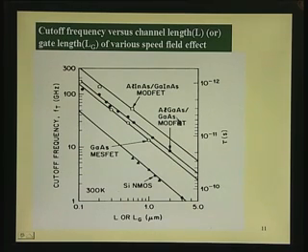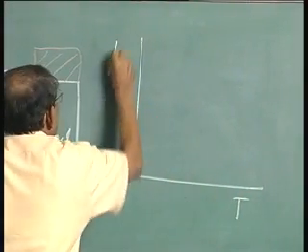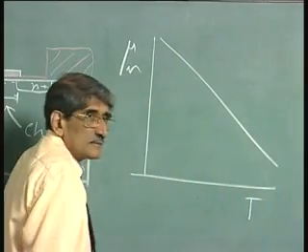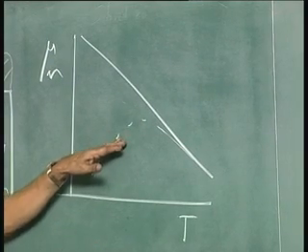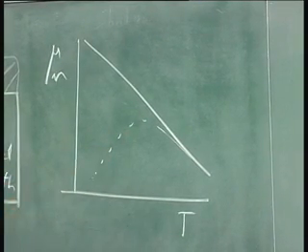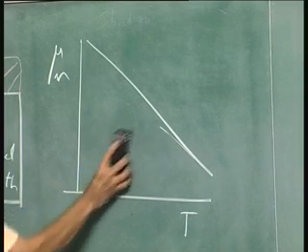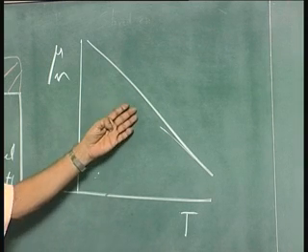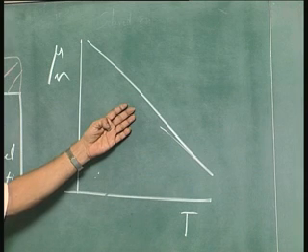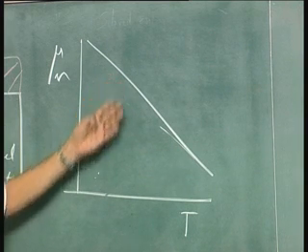Okay. And here if you go to lower temperatures, you can get this curve up even further, because if you remember, we plotted the temperature versus mobility like that, and you had this curve here. I am removing that. That is the lattice scattering mobility. By separating the donor from the electrons, then the whole thing is like this. If I go down in temperature, you won't believe the mobilities you can get, thousands, tens of thousands, or 100,000 if you go to liquid nitrogen temperature.